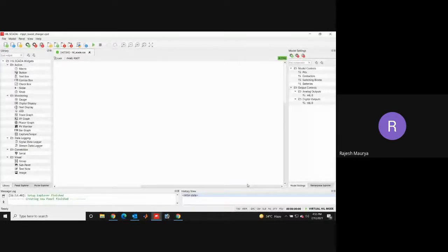In simulation, for a single phase inverter there are 4 switches. If you turn on 3 switches at a particular time, you will not find an error in simulation. But when you run that same model in real time and turn on the 3 switches at a particular time, then you will find this DTV violation error. Whenever you have developed a controller and that controller is violating the dead time, this error will pop up. This will pop up only in real time mode, not in simulation mode.